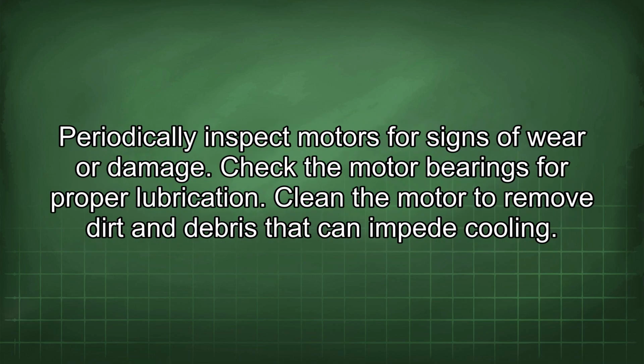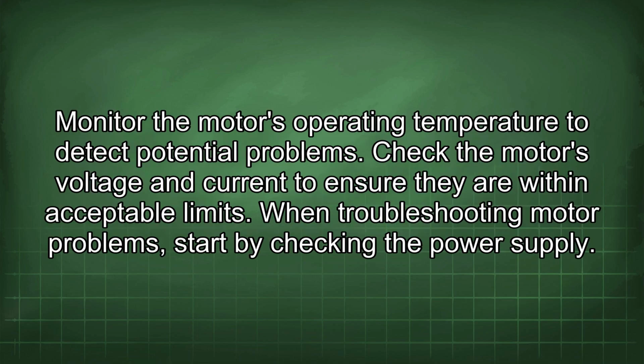Periodically inspect motors for signs of wear or damage. Check the motor bearings for proper lubrication. Clean the motor to remove dirt and debris that can impede cooling. Monitor the motor's operating temperature to detect potential problems. Check the motor's voltage and current to ensure they are within acceptable limits.